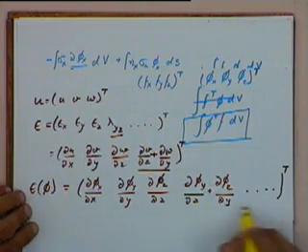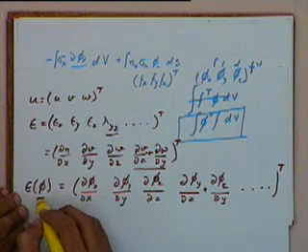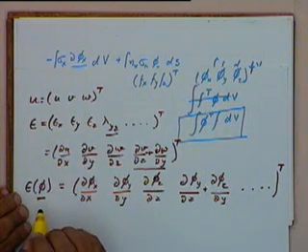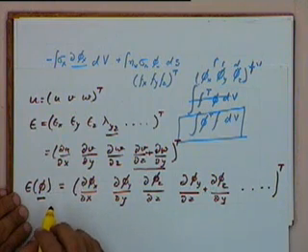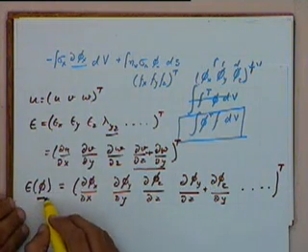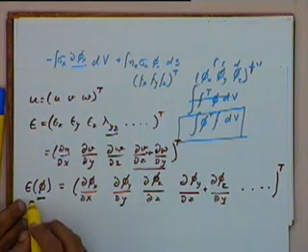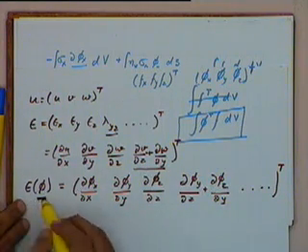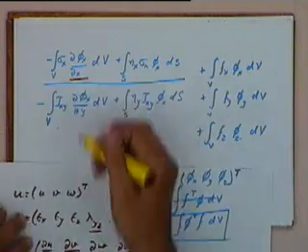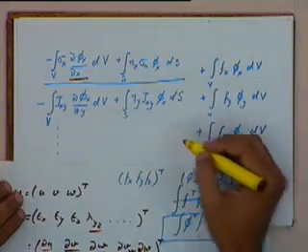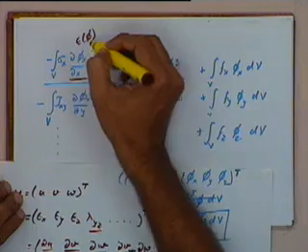Okay, so this vector is a strain that would be there in the object if phi was the displacement that was given, or if phi was the displacement field that was there in the object. So epsilon of phi is not the actual strain in the object, but the strain that would be there if this displacement phi was given. And if you look at these terms, first, second, this term is nothing but the component of epsilon phi.